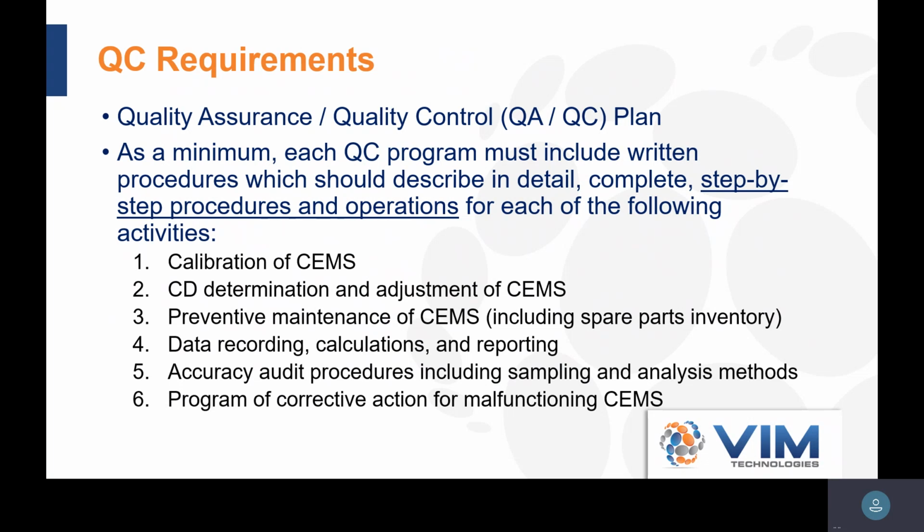But remember, it's a spare parts inventory of what you actually have, not a list of the recommended spare parts that you don't have. I'll say 80% of the QA/QC plans, obviously ones I didn't write, but 80% of the ones I do audits on, it'll just reference recommended manufacturer spare parts. Well, that's not the intent of the spare parts inventory. It's to show what you have on site so that you can make the repairs quickly and when necessary.